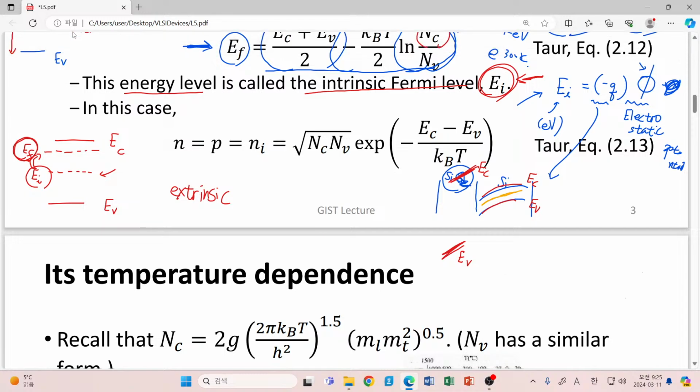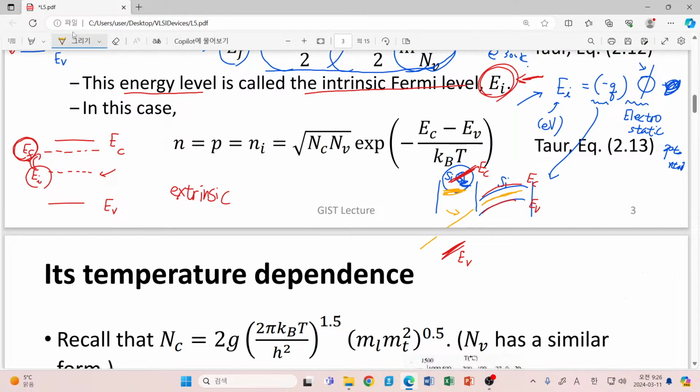And even in this silicon dioxide, instead of considering the spatial variation of silicon dioxide's intrinsic Fermi level, we just consider the change of our silicon's intrinsic Fermi level. That sounds quite weird.